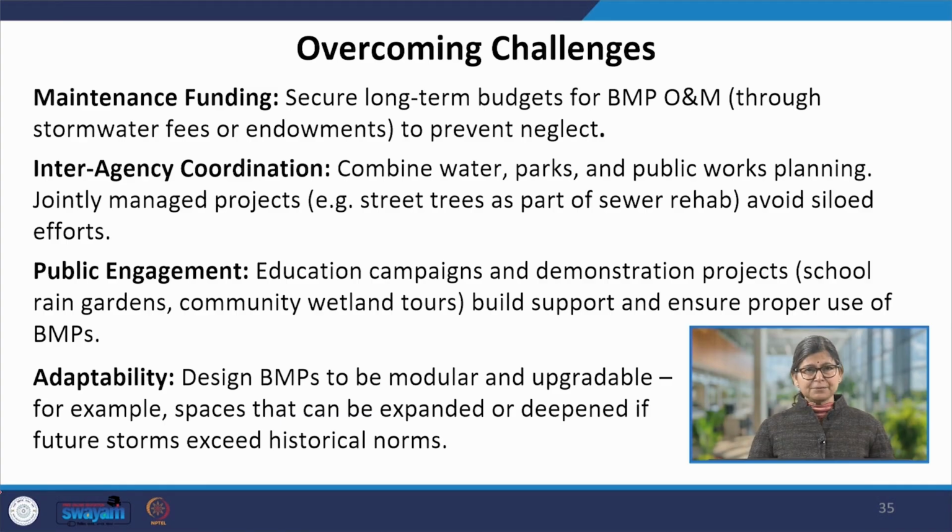Overcoming the challenges for BMPs. Maintenance funding: secure long-term budgets for BMP operation and maintenance through stormwater fees or endowments to prevent neglect, surely very important. Interagency coordination: combine water, parks and public works planning, jointly manage projects like street trees as part of sewer rehab. That will avoid siloed governance efforts.